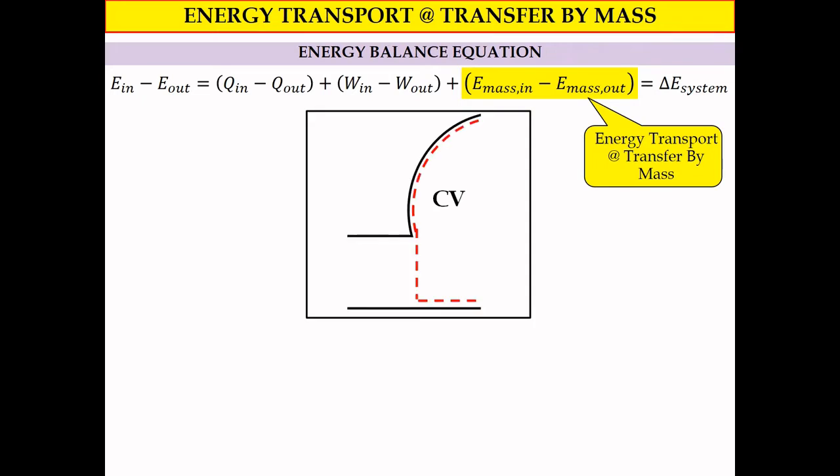If you refer to the previous control volume, when we discussed the control volume for the pump and the flowing fluid, we have mass flow in and also the total energy in into the CV. So the rate of energy that enters the control volume will be m dot in multiplied by total energy in. So we get the rate of energy flow into the control volume in kilowatt.